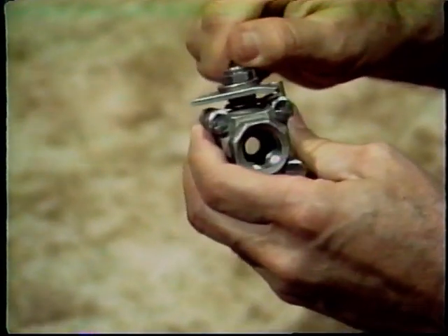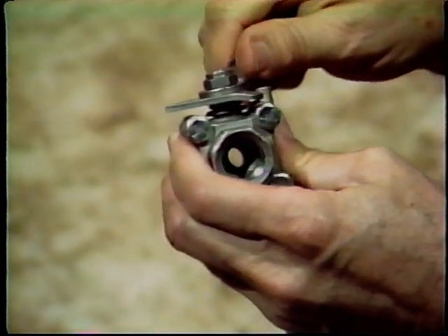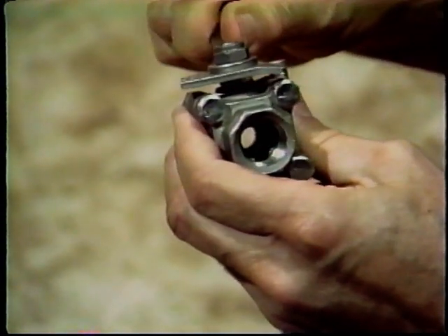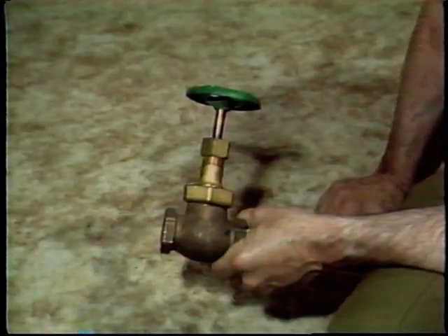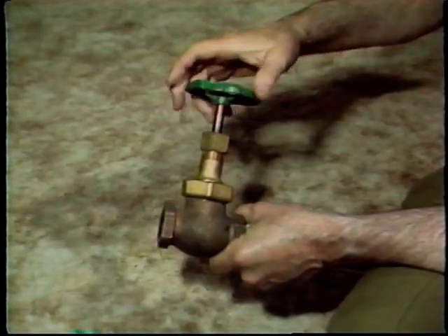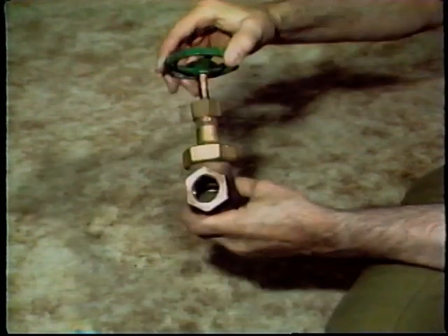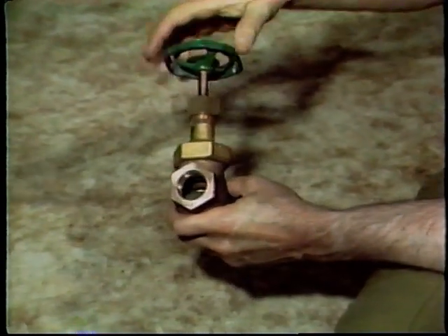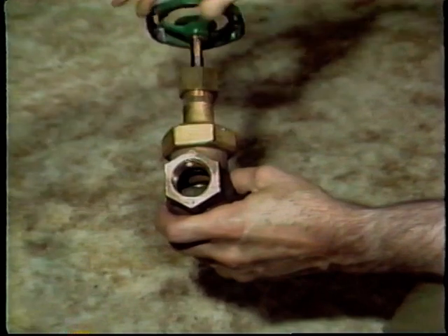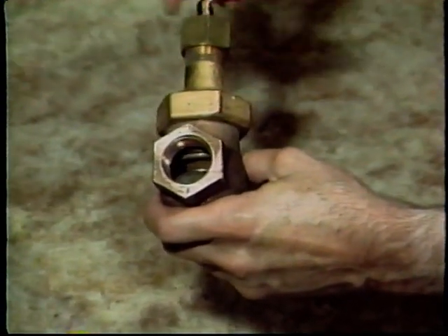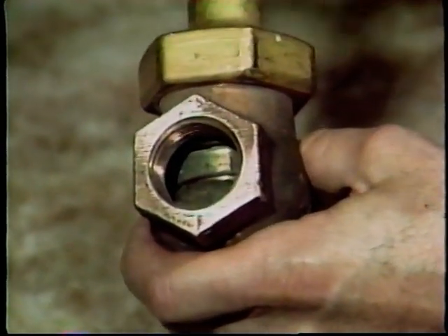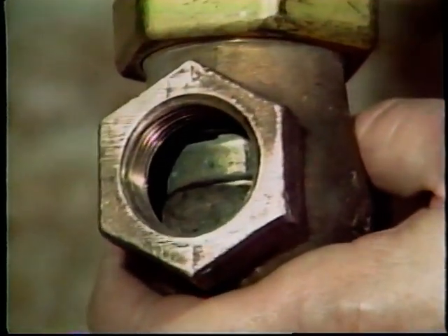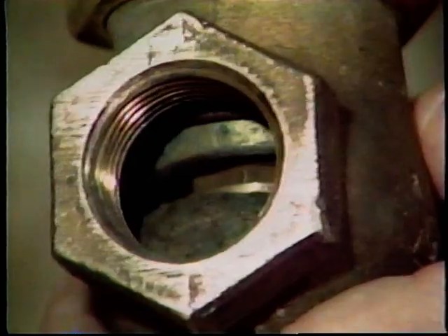Since a slight movement of the handle makes a large difference in flow, the ball valve isn't widely used for flow control. This globe valve is an adjustable orifice device. The disc or globe can be raised or lowered against a seat that has been machined into the valve body. Since this action changes the cross-sectional area through which the fluid passes, the flow rate can be regulated.